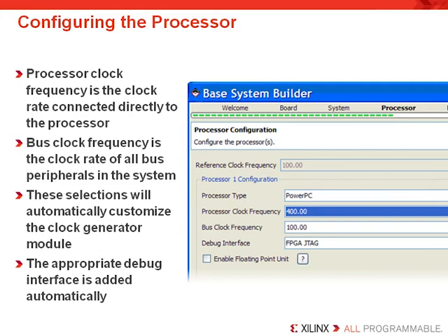But the real question again is, how fast will the system run? The answer is that it simply depends on the number of peripherals and how many buses your design has. Simply put, the more logic, the lower the maximum speed. It also depends on the family of the FPGA you're targeting and, of course, the speed grade. Recall that each family has different performance. However, to get peak performance, most designers are only adding a couple of peripherals to the system. If your system is like that, then top speed should not be that difficult, but unfortunately you won't know until you build the hardware and try to place and route the design.